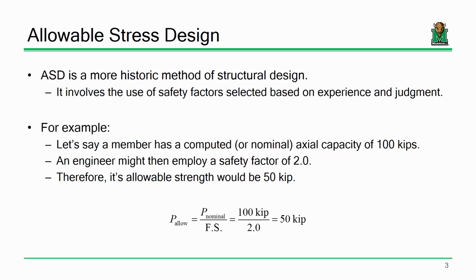Now, I'm a table salesman, and I'm going to sell this to a number of consumers who are going to put this in classrooms and offices all over the world. Do I want to tell these consumers that this table can withstand 800 pounds? Probably not. Probably what I would do is say, let's put on the package that this table has a maximum capacity of 400 pounds. Okay? So that way, there's a little bit of a factor of safety built into it.